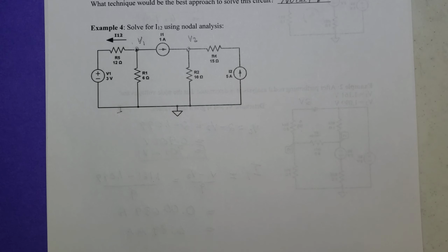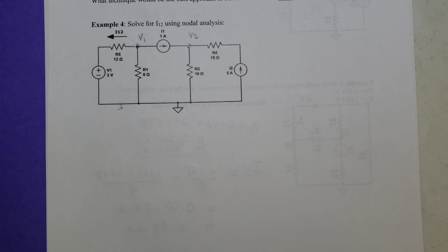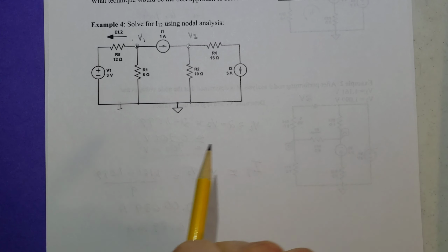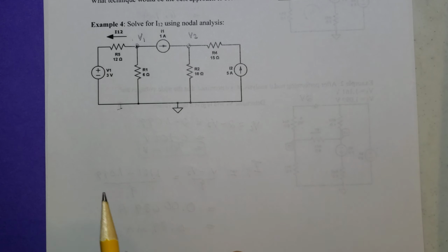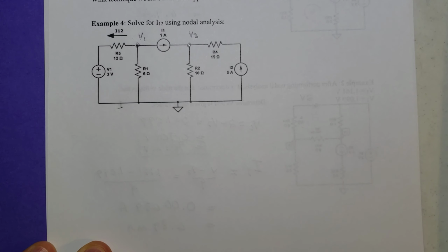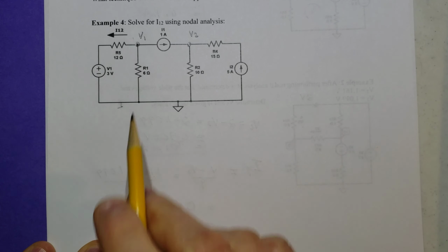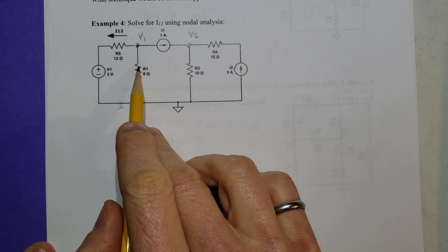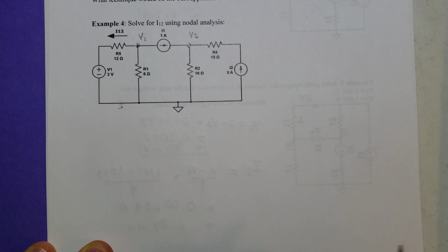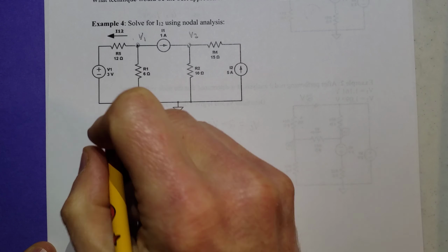So with this then, nodal analysis has one drawback to it in that we get a lot of denominators. And we're going to have to factor out the lowest common denominator and multiply by the greatest common factor. But that's an extra step. We want to make sure to do that, though, because it's a nightmare if you carry through all those denominators. But we plow ahead. Okay, we're going to have three terms in the first equation. We're going to have three terms in the second equation. We write them through, we chug through the algebra, and we'll get our answers at the end.